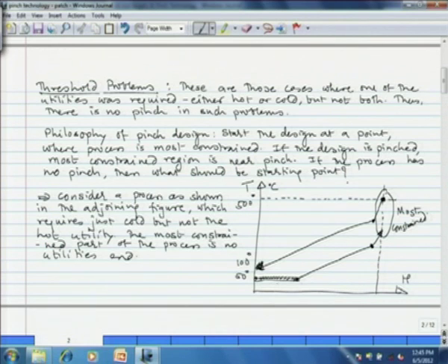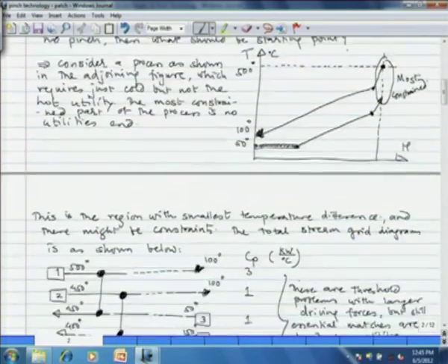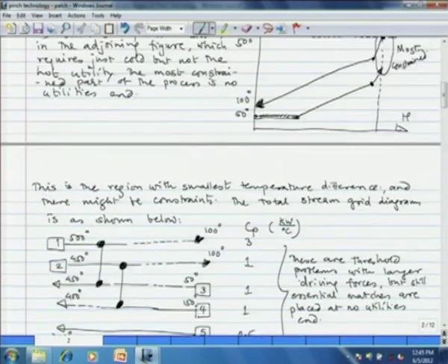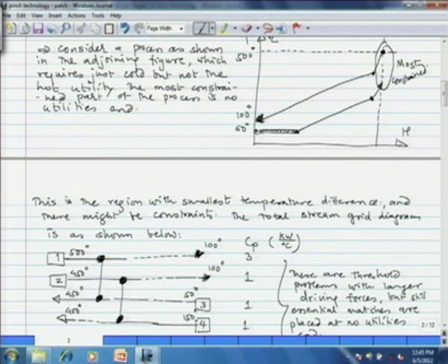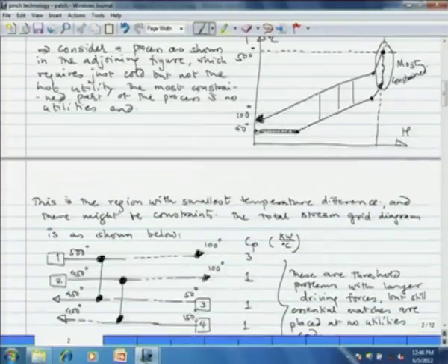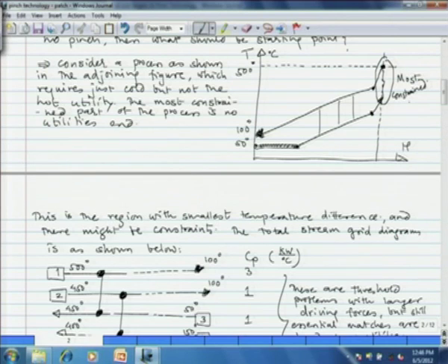On the other end, you have cold utility, which you can vary. And then what we find is that the most constrained region is the region with the minimum temperature difference. Like if you see the temperature difference in these regions, we have the minimum temperature difference between the two composite streams at the hot end problem or the most constrained region, and then we start our design at that point. Okay. That means, we start our design at the point of the no utilities end, the hot end.